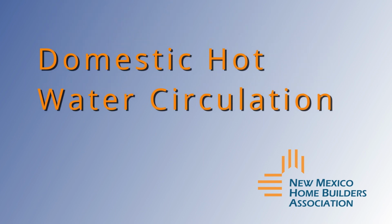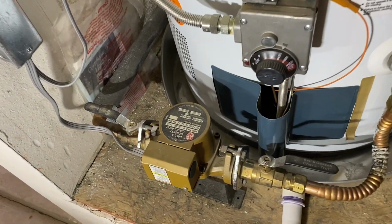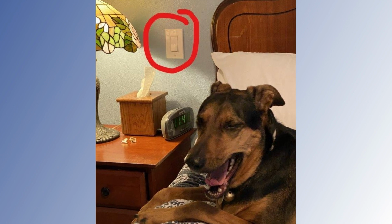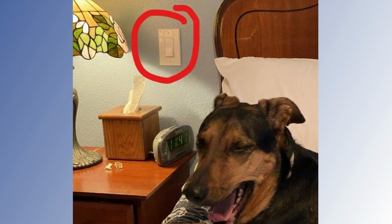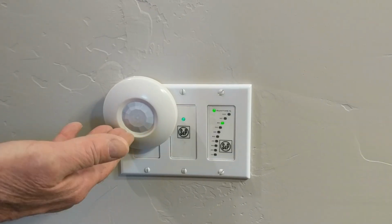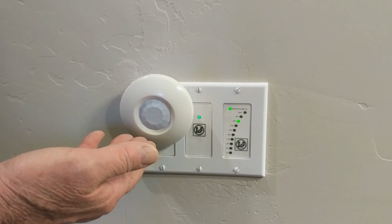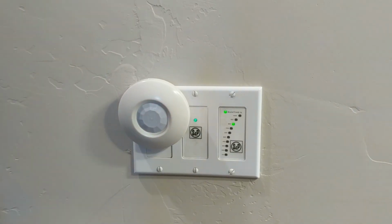On-demand controls are now required for recirculating domestic hot water systems. This can simply be a wall switch that can be turned on, wired to a timer and the pump. Also, there must be a control to limit the temperature of hot water returning into cold water pipes to no hotter than 104 degrees.